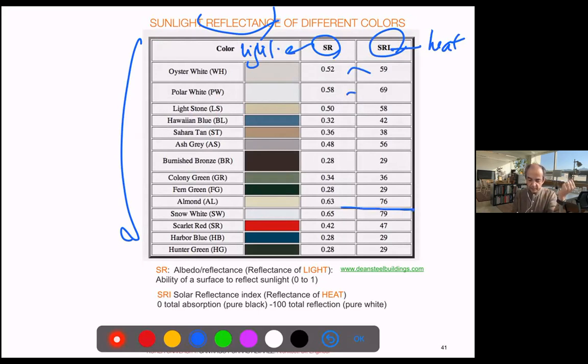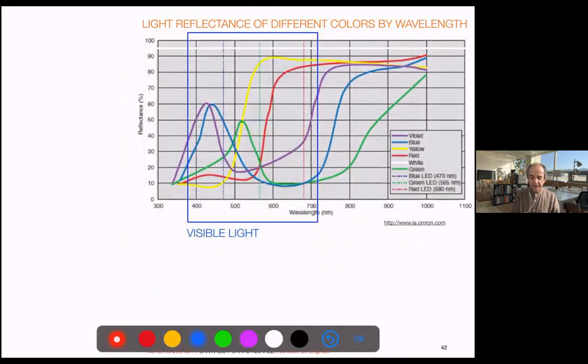And you see that the whitest we have, Snow White, will go almost 80% of reflection. And we don't have the pure black, but blacks will go probably 10–15% reflection, the best we can do, right, in absorption. So you have a scale. Of course, depending on the colors, the reflectance is different. That depends on the wavelength. This is physics. We will not elaborate on that, only telling that the visible light is around there. If we have several different tonalities, it may change a little bit, but we always consider white light as a reference, right? And we know pure white is just an ideal.